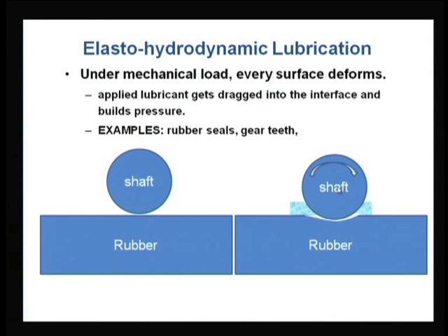If there is a deformation and if we pour the lubricant, because of the rotation, lubricant will be brought into this kind of interface, which can retain the lubricant for some time compared to a straight surface. It is making a shape in such a manner that it can act as a reservoir for the lubricant.